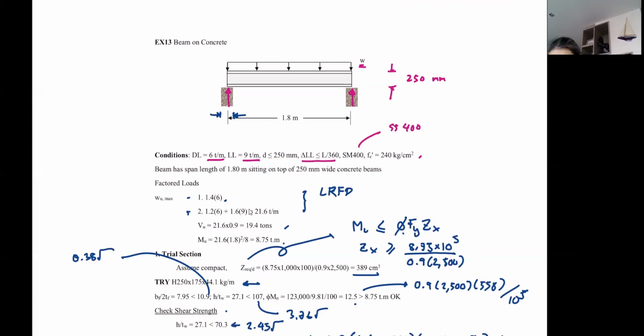To say that this will be strong enough to provide the bracing, we perhaps need to check whether the anchor bolts can sustain the force generated by the tendency of the beam to move as well. Good point, but generally it should be enough to prevent lateral torsional buckling.